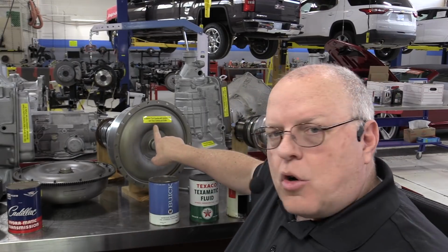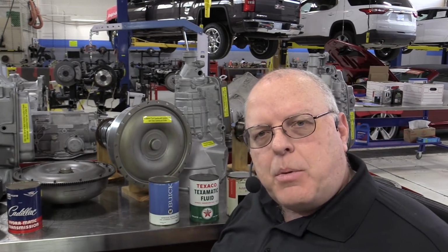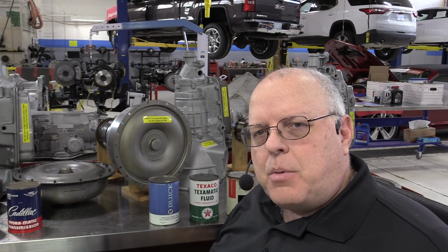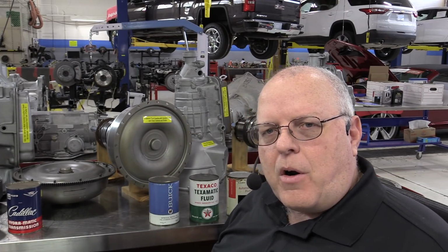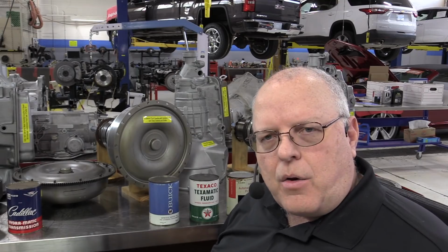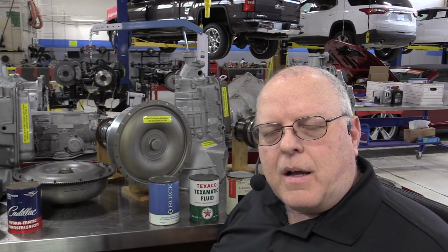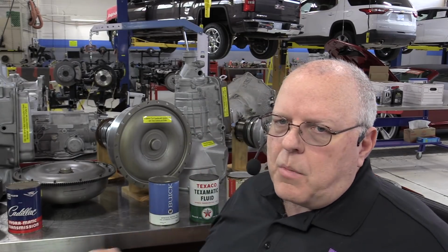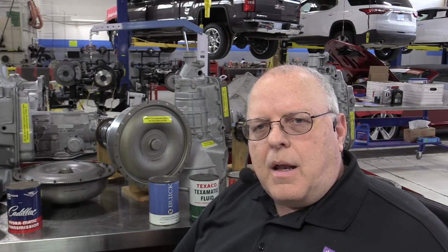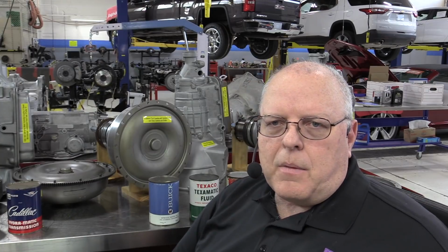And this torque converter has 3 turbines with 3 input shafts. And each input shaft is connected to a different part of 2 different planetary gear sets inside of this. They call it a 3-ratio transmission, but it's much more than 3 ratios. It has a minimum gear ratio, like a low gear ratio, and it has a maximum gear ratio, like the overdrive or direct drive that an automatic transmission would have.